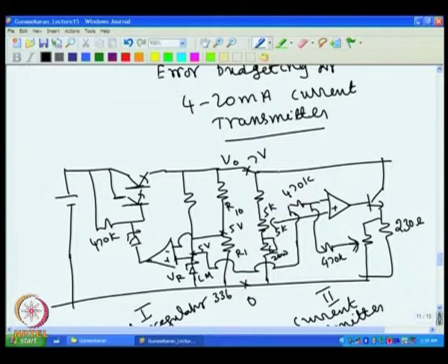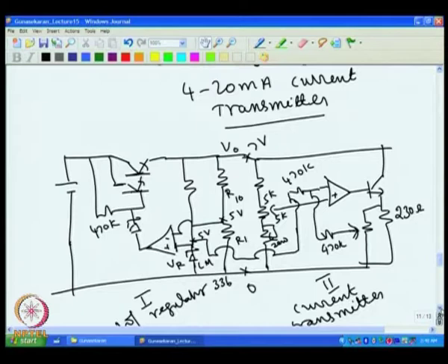That means this voltage is 5 volt. So, you got 2.5. So, this has to be minimum 2.5. So, we have 2 volt as designed for the potentiometer. So, 5K has 2 volt, that means 2.5 will be the voltage across this. Then 2.5 plus 2 is 4.5; if it is 7 volt, then the remaining 2.5 has to be across this. So, 2.5, 2.5 and 2, that is the voltage across these points. So, 2 volt here, 2.5 here, 2.5 here, those are the normal values.